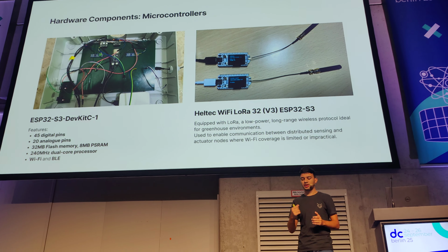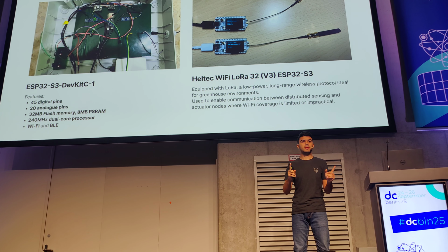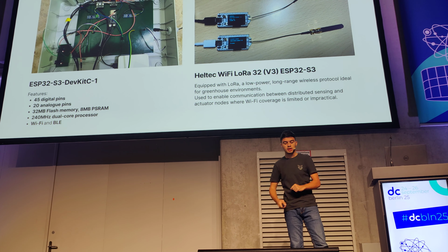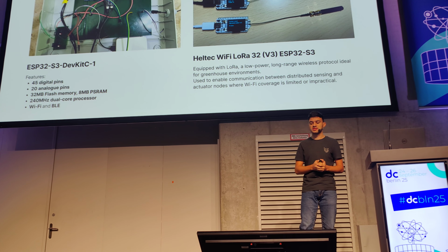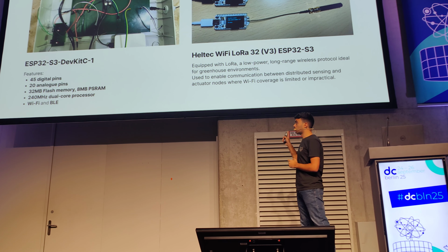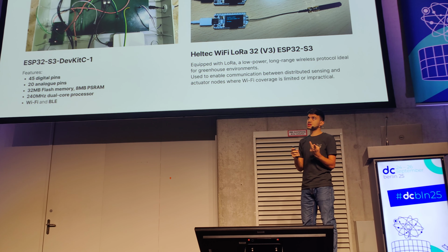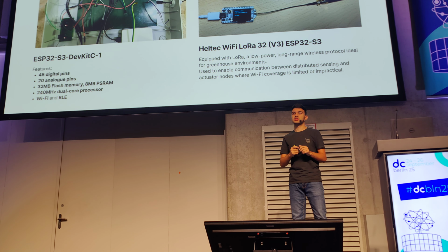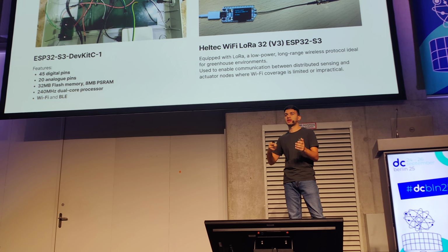It has Wi-Fi and Bluetooth Low Energy, so in this case we will be making API requests to a server, which I will explain later. But thanks to that, we will have the necessary pins and interfaces to make the system work. Additionally, later on, when we have 2 systems with the actuators and sensing, I used a LoRa-enabled ESP32, which is a long-range wireless protocol, and this will make the ESP32s talk to each other seamlessly so that they can transmit data and the other one can react upon the data that is received.